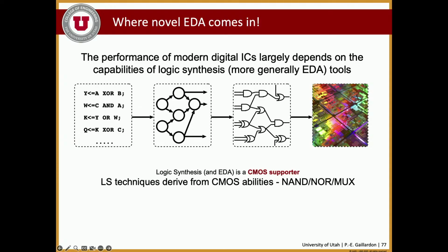And logic synthesis has always been a CMOS supporter, right? It's been designed that way because MOS transistors are good at implementing NAND and NOR gates. Therefore, all the tools have been exploiting that. So the data structures are based on that. The algebra that is used in these tools has been based on that, right? So it's designed to implement NAND, NOR, multiplexers.